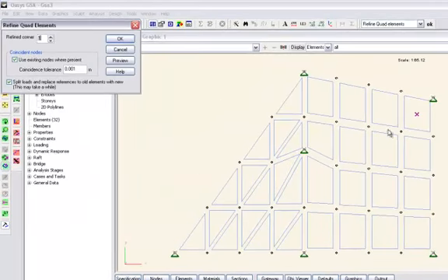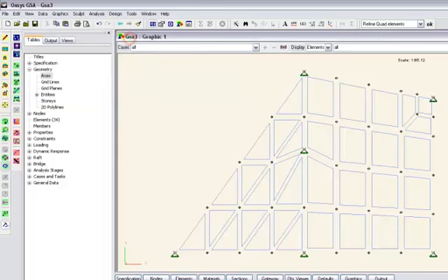That goes to corner 1, 2, 3, and 4. So if I do corner 1, for example, it's trying to refine that corner. It wants to be corner 3, and that gives us a finer mesh to deal with the change of stress contours and get more accurate results.